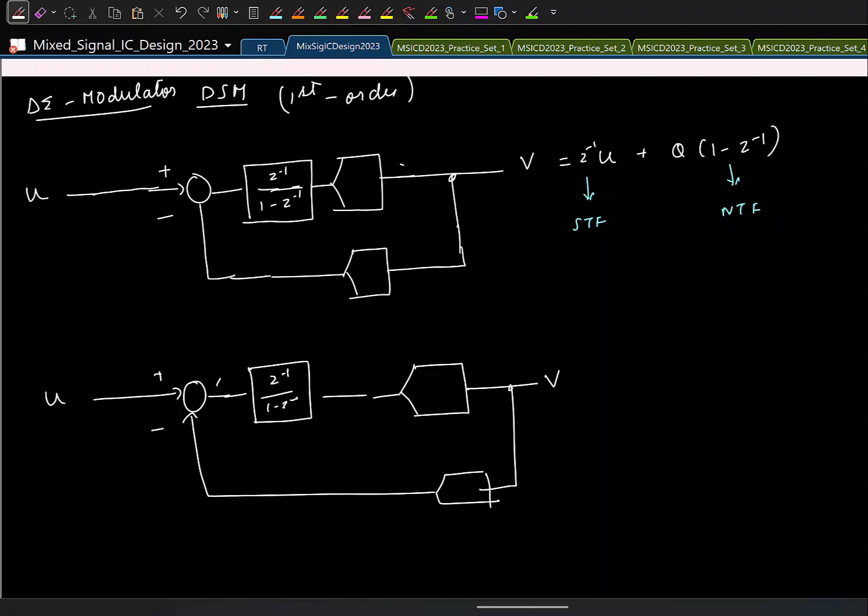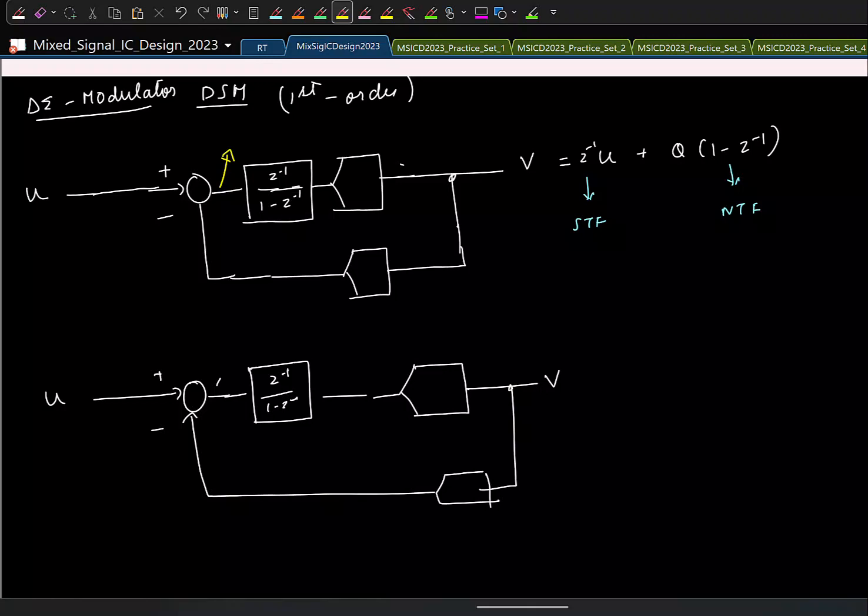Okay. So again, this negative feedback loop is the underlying thing almost everywhere, right? And if I do this now, you should be able to tell what is the DC here. If I look at this signal, I call it some, I don't know, I'll call this error signal E. If I look at the average or the DC of E, what will this be? It will be exactly 0, right?